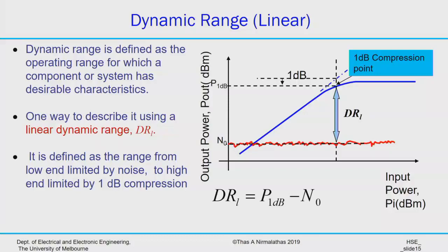If you're designing a digital system, it is about the voltage, low to voltage high separation, how much there is. And in the analog sense, dynamic range can be lots of different things, all right? So there are lots of different types of dynamic range people will use to differentiate what they mean. But in all cases, it somehow gives you an operating range over which some parameters are managed well. That's what it means. So in this case, often the dynamic range can be used simply to tell you the safest gain range over which you can operate.